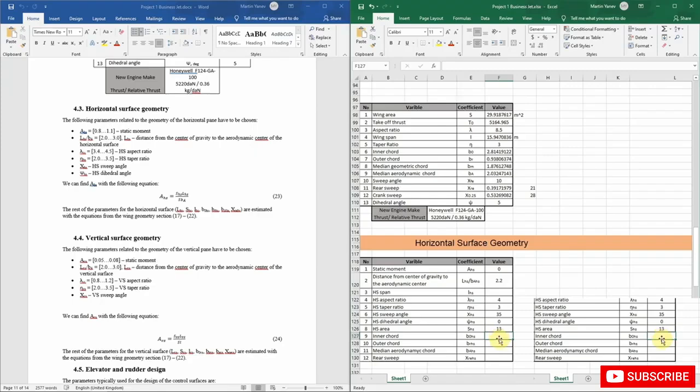But let's see, maybe we'll change this number after we see how this equation stands. So now we can estimate the span of the horizontal stabilizer, and this will actually be equal to the square root, so it's the same equation as the wing, square root of the area of this surface multiplied by the aspect ratio. So we're going to multiply this by the aspect ratio, and we're going to get that the span is about 7.21, okay, and that's it.